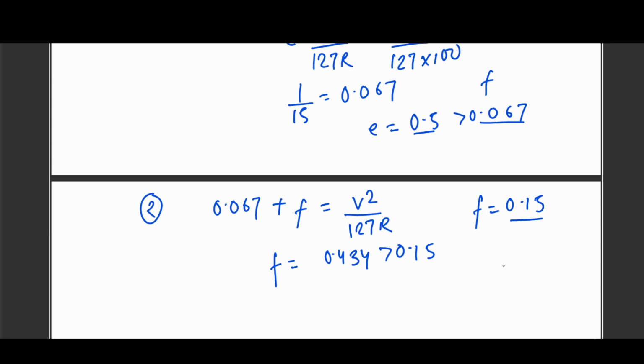So we get to know that for this design speed, that is 80 kilometer per hour, our maximum super elevation provision and the maximum coefficient of lateral friction will not be sufficient. So we have to decrease this design speed. For this we now have to provide the maximum value, because this is the allowable value. We cannot provide more than this.